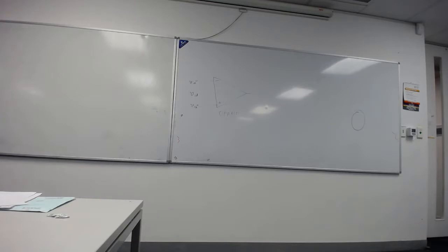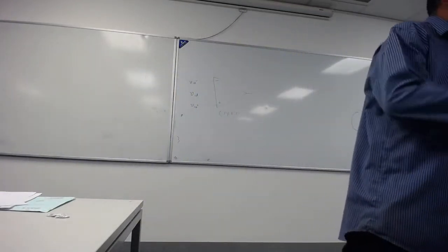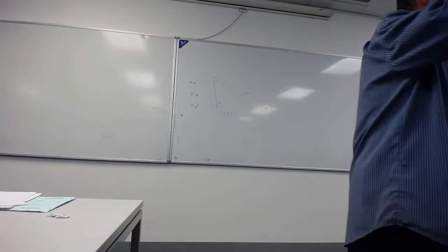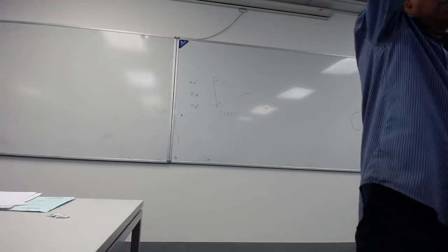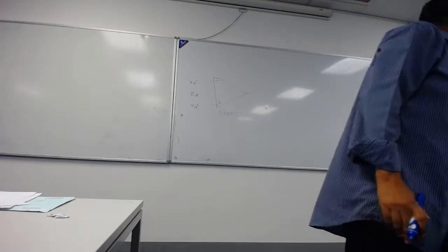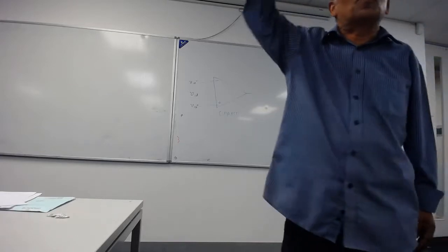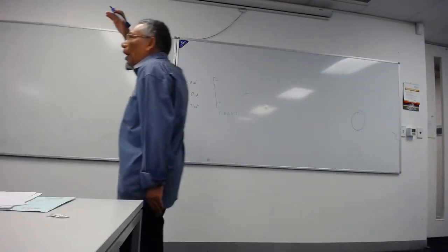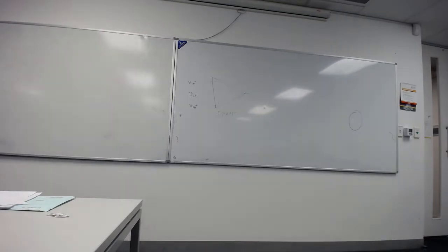So clipped to what? Your rail voltages. Yeah, so it's clipped to a certain voltage. What is that clipped voltage? Close to the supply voltage. Yeah, what is that clip level? The clip level of the op amp is related to which voltage?